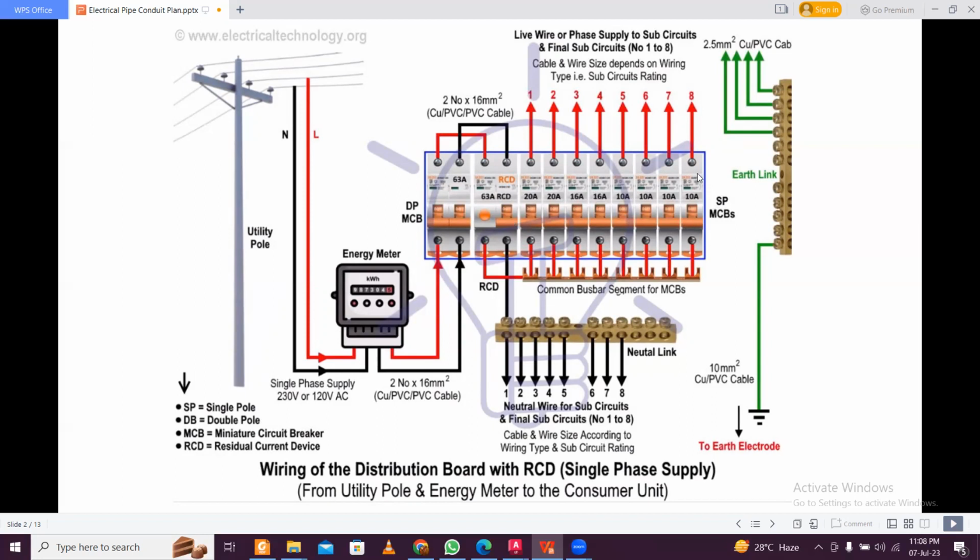So it basically depends on the architectural plan. Suppose it's a bedroom, then we need to have switches in some areas. If it's a living room, we need to have switchboards in some areas, near the TV. So like that, we have to do things. So basically, the architectural plan, or the arrangement or purpose of the building, determines the way in which these conduit pipes are placed.